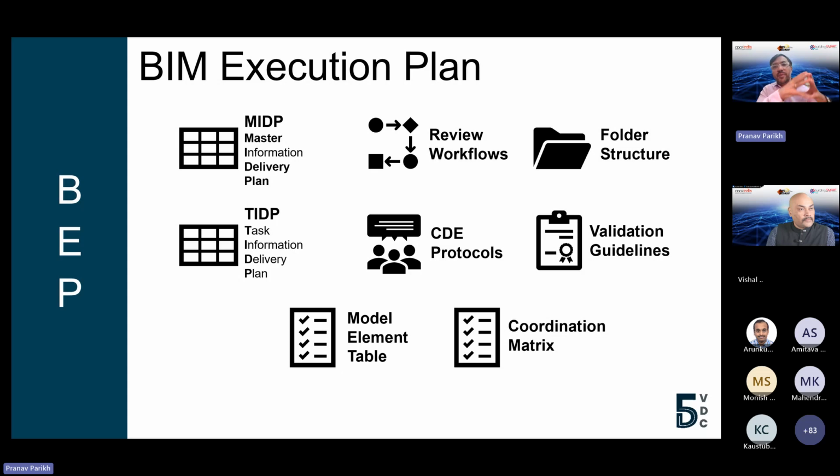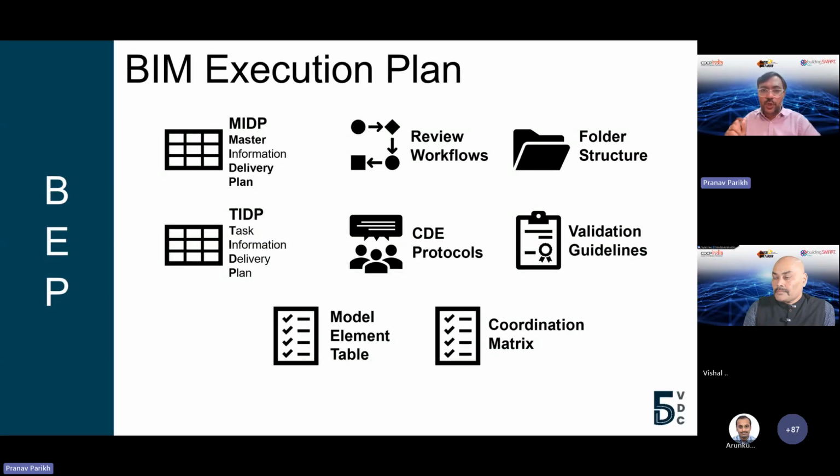Clear? So if you remember, when we talk about WIP, shared, published, review workflows, exactly in depth, it is defined in BEP. It is how the folder structure would be defined in BEP and EIR, the common data protocol documents. MIDP, TIDP is more about further breaking down my BIM execution plan into granularity of information delivery, when I will create architectural model, when I will create structural model. In structural model, furthermore, if I go into task, when I'm going to get foundation drawings, when I'm going to create the superstructure drawings or superstructure model. So MIDP, TIDP is all about that.